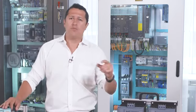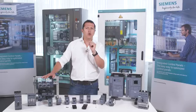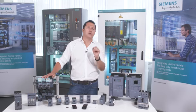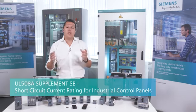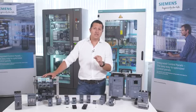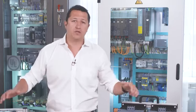In the case of US standards, UL 508A is the only approved calculation method by the National Electrical Code, or NEC, to determine the overall SCCR value of an industrial control panel. Here, the detailed description and calculation method is in Supplement SB. Besides the calculation, testing is always an option, even though this is not often used for industrial control panels, because this is time-consuming and costly. In Canada, the CSA 286, similar to UL 508A, bases the short-circuit current rating on tests or default ratings.